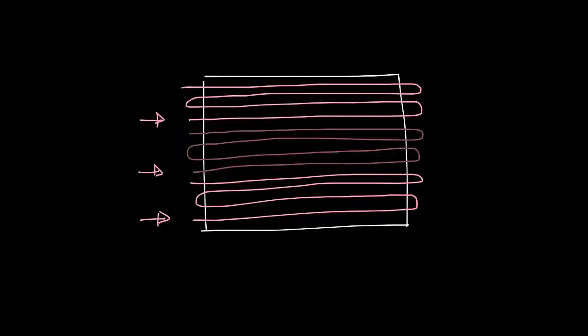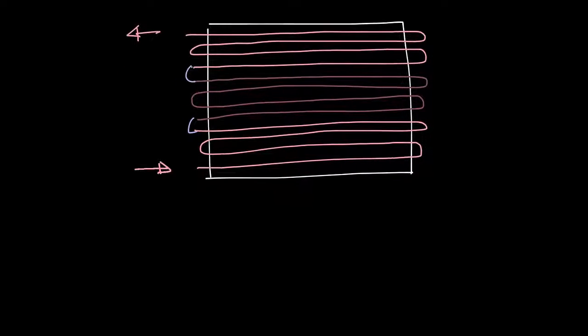But wouldn't it be easier if we connected our 3 circuits into one big circuit? So we connect here and here. And now let's get rid of our arrows from our 3 entry points. And we would just have water coming in here at the bottom, and it would exit the coil at the top. So this may be possible, but there's a couple things that circuiting in a water coil does.